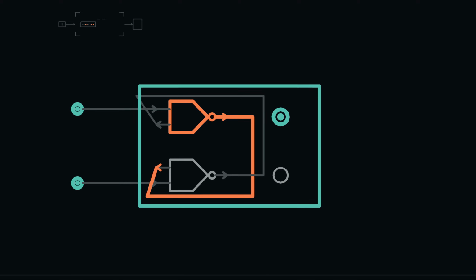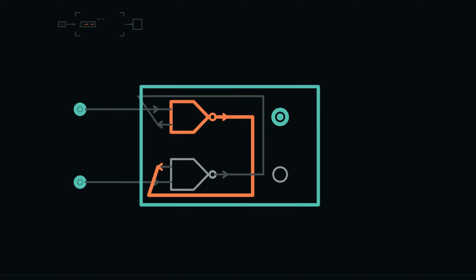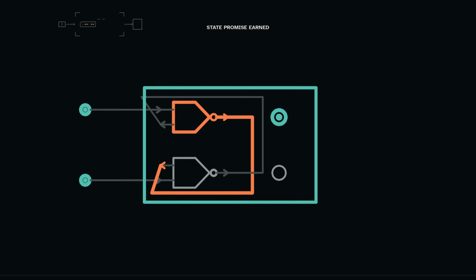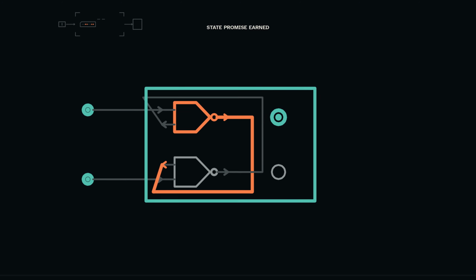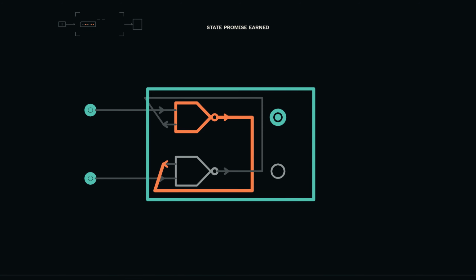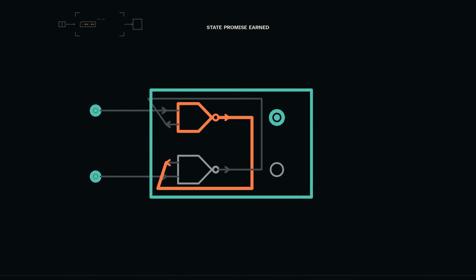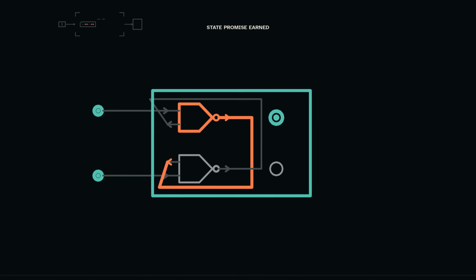The stored bit is not detached from physics. While powered, the feedback network continually maintains physical output conditions representing its state. Noise margins, delay, loading, and power limits still apply. Remove power from this ordinary volatile latch and the maintained conditions disappear.